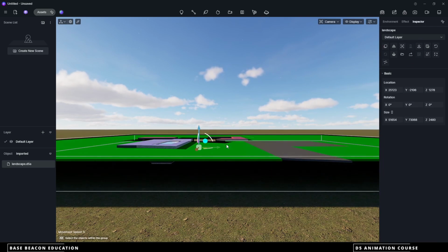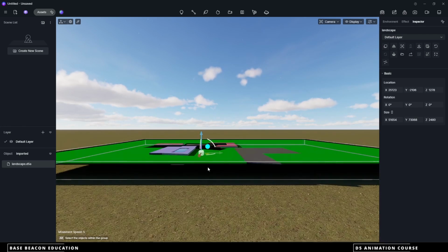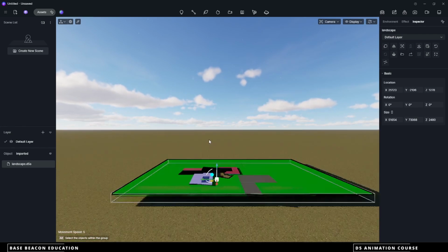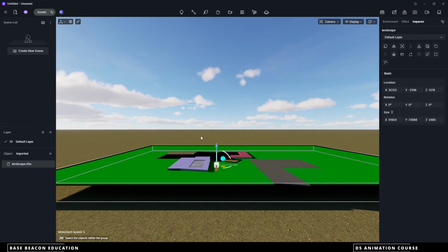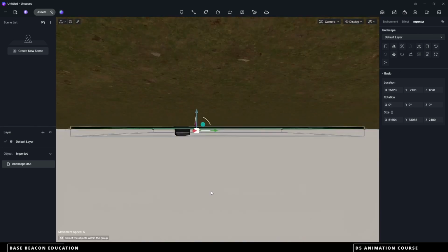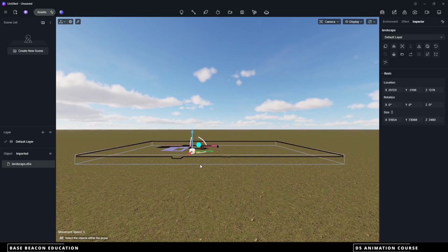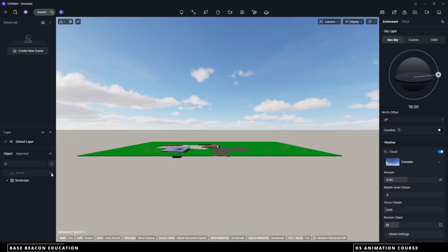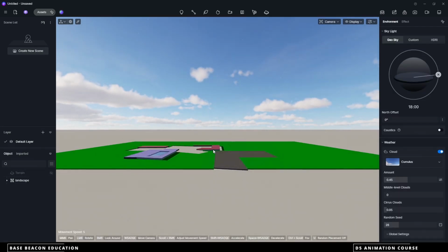But now the reason why I was turning on the surveying point is that you can see, how do we know that all these files are in the same place, at the correct survey point coordinates? So I just go onto my inspector here and then I click sync coordinate. So now this will be exactly where it is supposed to be in Revit. But let's switch off this default landscape. Let's go to objects and switch off the terrain here so that we can see ours.